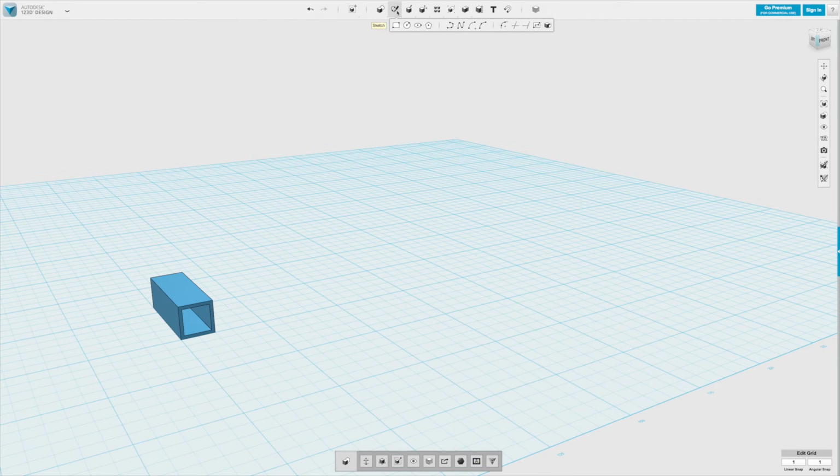We're going to create a pattern along a path. In this case, there is a nice way of making it along a curved path, but the problem with that is that the distance between the pattern pieces is not going to be equal. You'll see what I mean in a second. So for now, let's just go to pattern, path pattern.